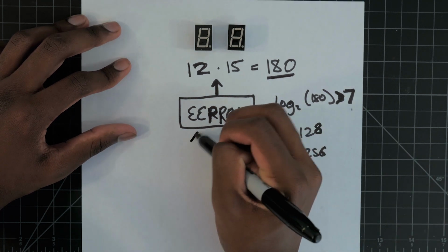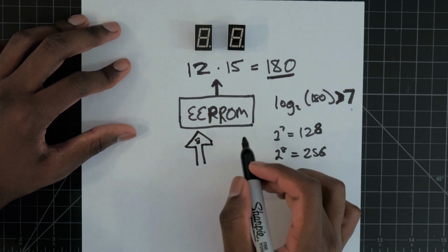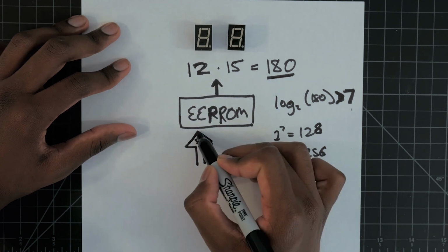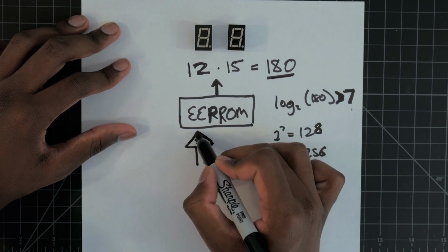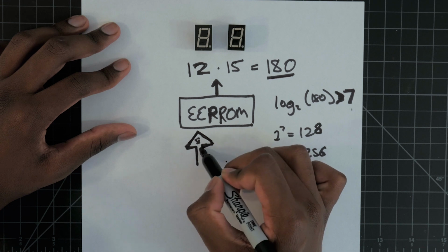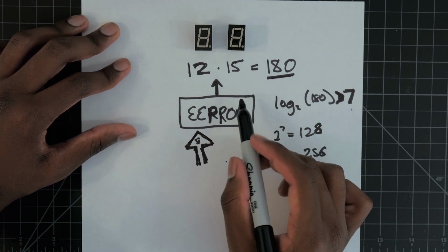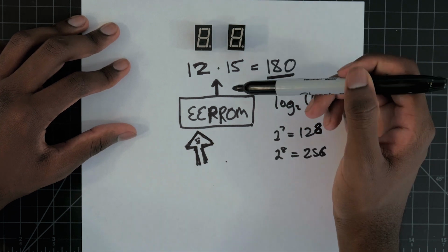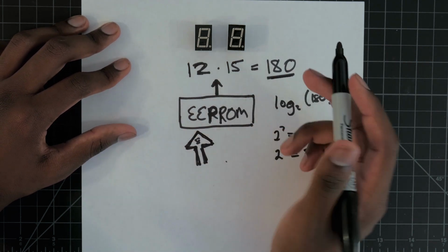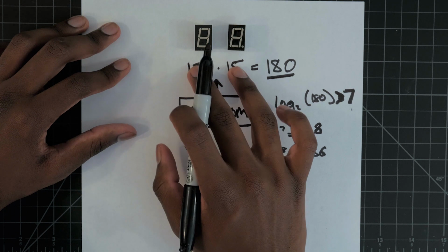So for starters, we're going to have 8 bits travel into this EEPROM. Now these 8 bits will tell the EEPROM what the time is that it needs to be displaying on the clock. Now for those of you who remember from the 8-bit CPU, the EEPROM only has enough outputs that it can only drive a single display at a time, but we've got 2 displays.